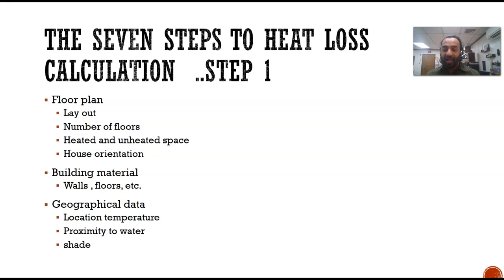So I will talk also about the house orientation. Why does it matter? It matters when it comes to summertime and the heat gain, but it also matters for us if the windows are facing more south and you get more sun during the day. That might help you a little bit when it comes to heating, but we do not account for that because we have no guarantees that the sun will shine every day. True?